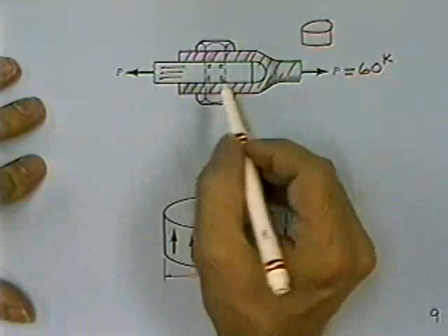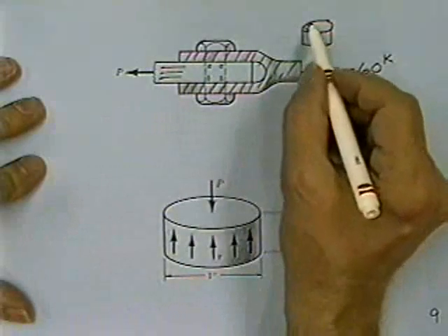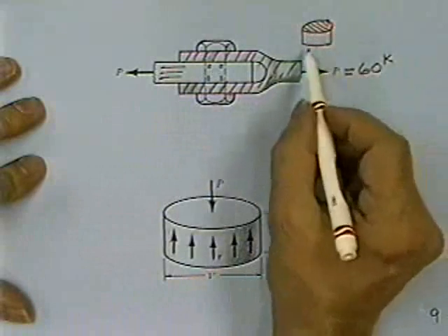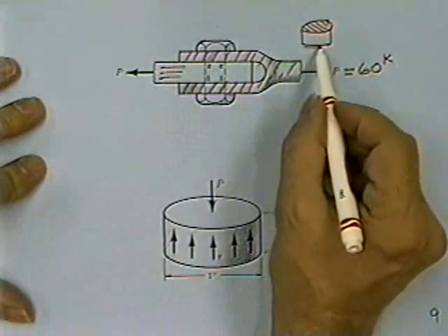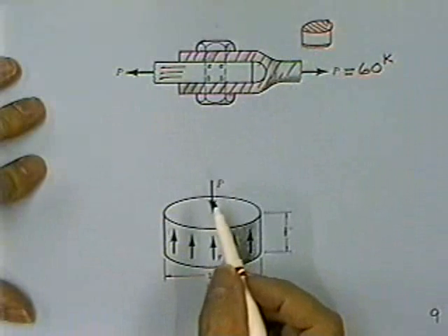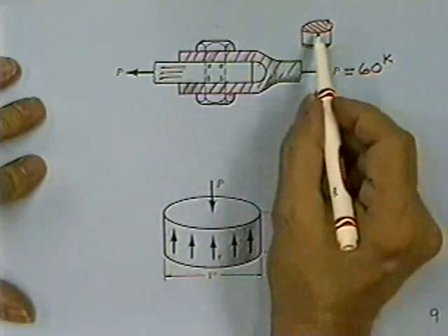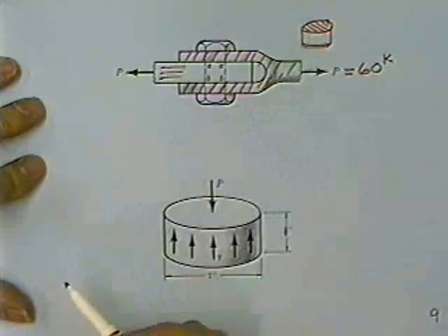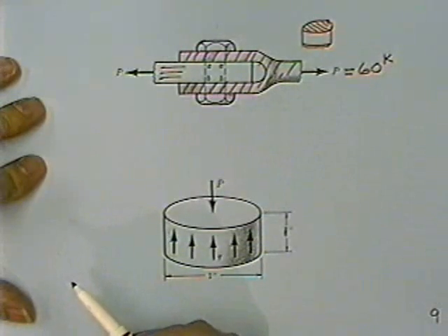And when these little pieces fell on the floor, you see this piece of the bolt is nice and shiny, and you also see this area underneath here is nice and shiny. All the rest of the bolt is nice and rusty. Well, that nice new shiny surface that you see is the failure area. That's how you tell whether or not you should be using the cross-sectional area of a circle or the cross-sectional area of a cylinder or whatever.